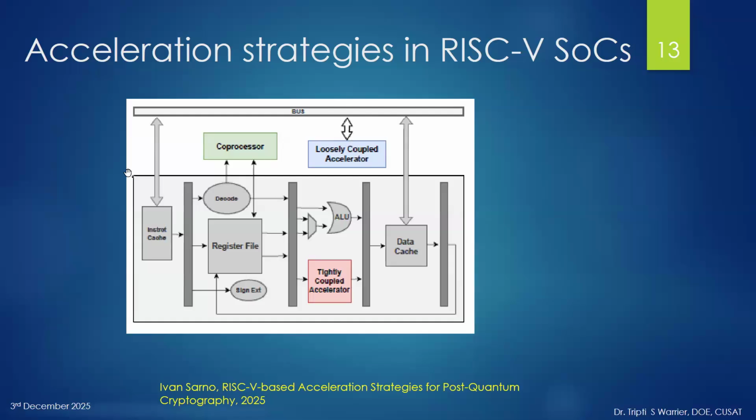And then, when you write C programs, you will map your tasks to this accelerator using memory map. So communication of the core and the accelerator happens through the common data bus that is there. Instructions will be given through the bus, and the accelerator will work on it and then broadcast it in the bus, and that data will be updated in the memory. So that's how it happens.